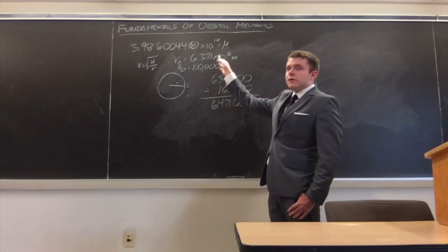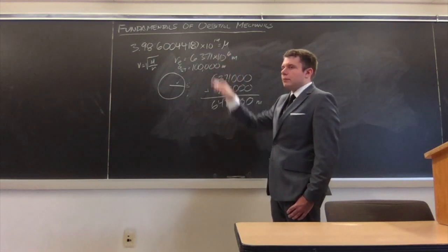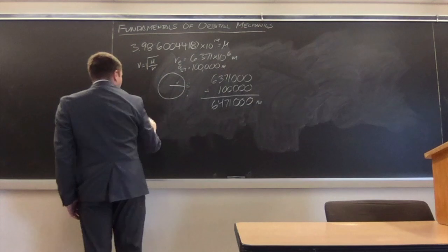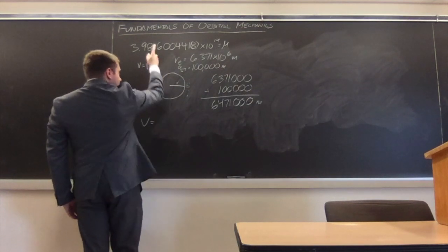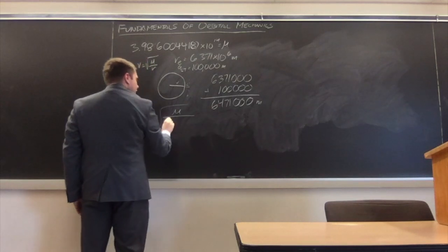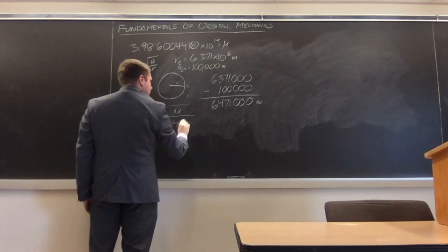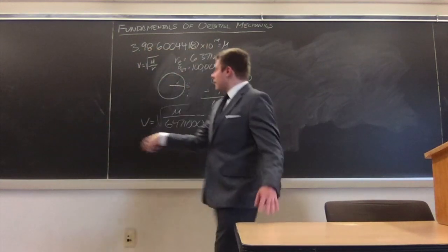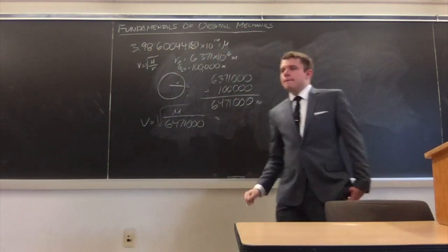I won't try and translate this into kilometers because it's a very annoying number to play with, but I encourage anyone in the audience to come up with our orbital velocity for that number, square root of mu over our target radius, which is 6,471,123. So, what is our target velocity then? I got 7,848.